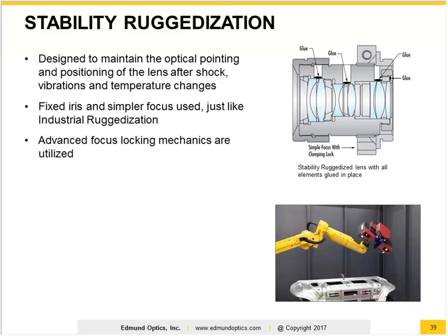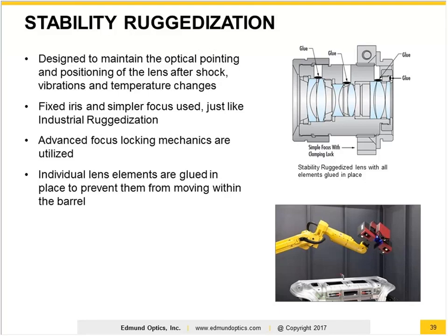Positioning of that set screw so it's easily accessible isn't always done very effectively, depending on the system. So this is something you want to consider before you build out the mounting or enclosure parts around the camera, so that you can actually access it and, after you focus the lens, lock it in place. There are some extra things to keep in mind when using that level of clamping for that sort of ruggedized lens.